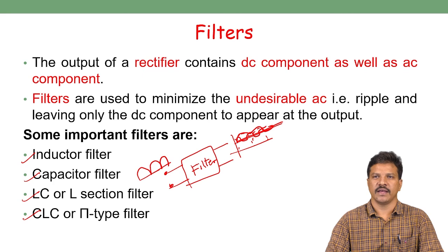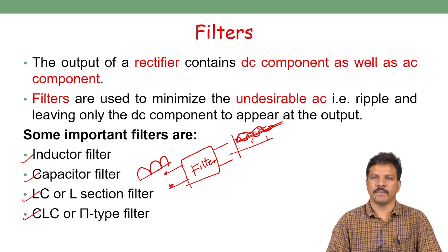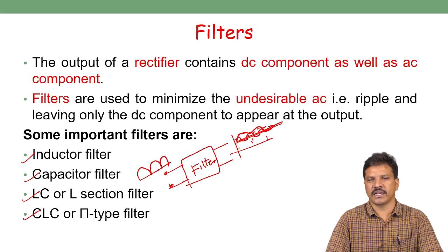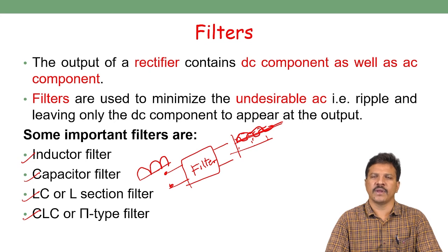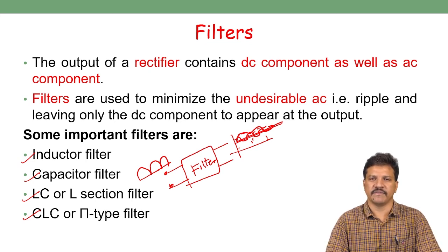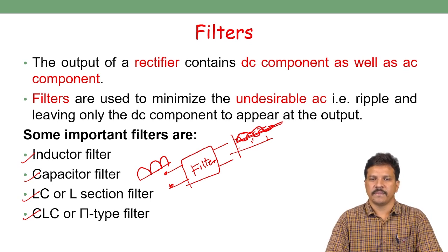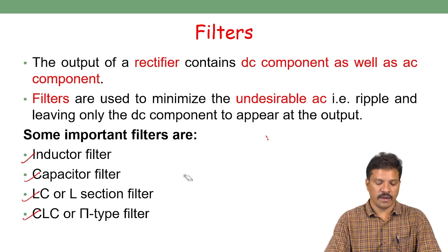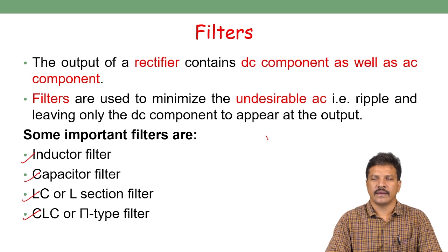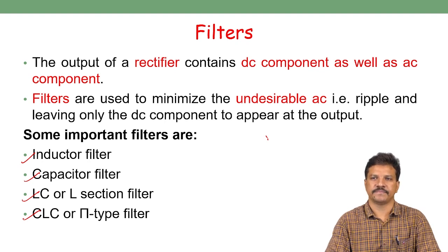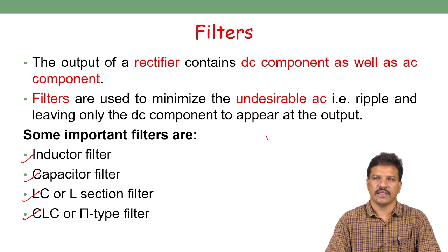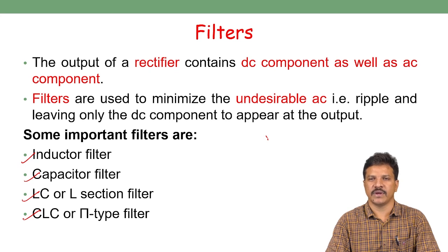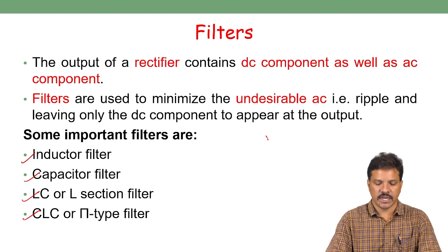which will be used in the power supply block. The circuit which represents the filter is very simple because of the elements used in the filters, like inductor, capacitor and combinations of those. Based on their properties, we can use in electronic circuits the L filter, C filter, LC filter and CLC filters, so that we can get perfect DC. Most probably we can avoid a heavy load inductance compared with the large capacitance. As much as possible, the capacitance value is very large and the inductance value is very small. So this is all about the filters.